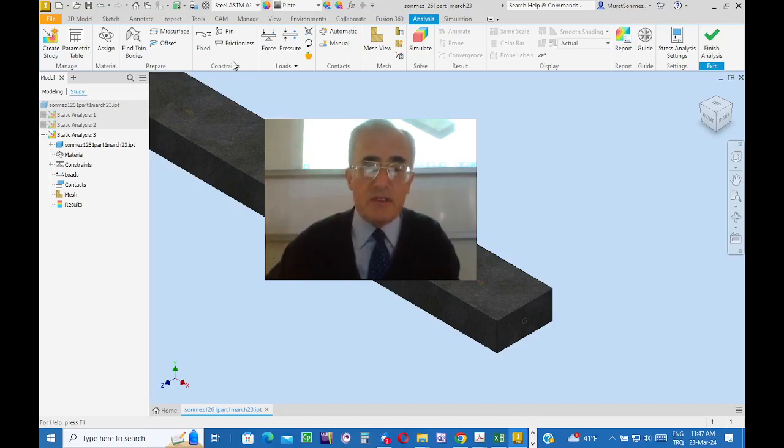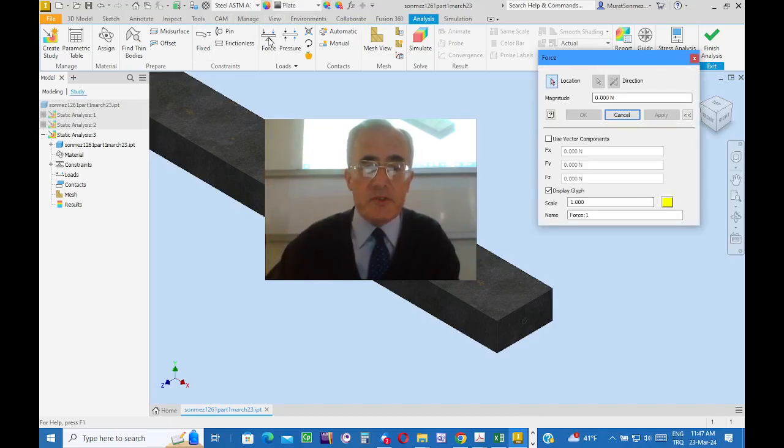One boundary condition. Click on the force button. The boundary condition is a force type boundary condition. It is acting over the surface, already split. Yeah, the magnitude of the force, 8,500, or say 9,000. Yeah, 9,000.